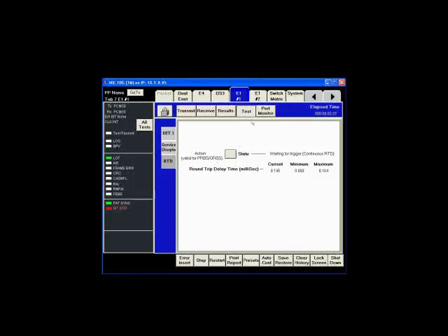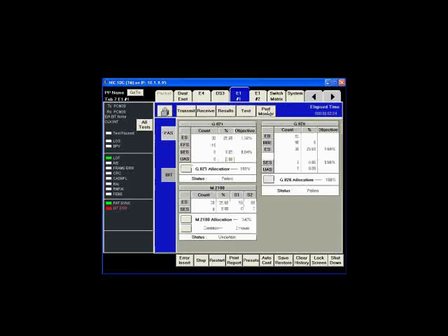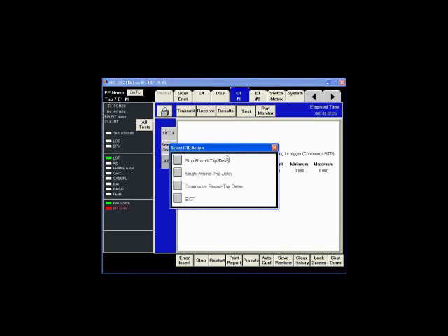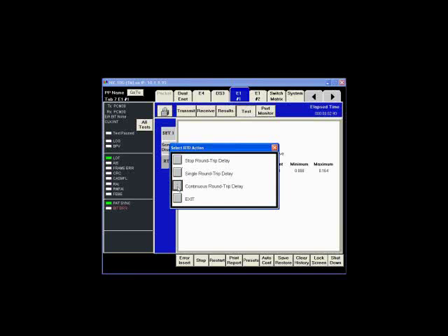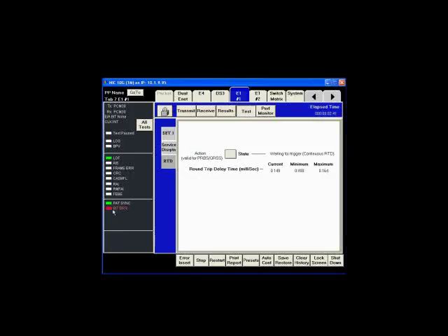Okay, and then we get to performance monitor. Actually, let's turn that off. And notice that, by the way, it wasn't detecting on the pattern itself. When I turn this to active, turn to continuous, we got bit errors because it's actually sending bit errors occasionally, and that's what it's triggering on, those bit errors. That's how it knows. The patterns themselves aren't long enough to do a round trip delay test because every pattern looks like another pattern and they repeat too often.